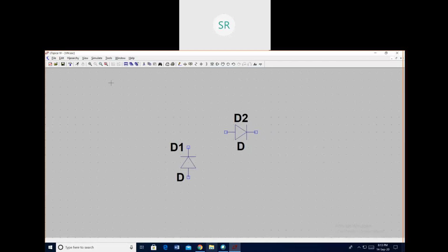So I want two capacitors. Capacitor 1. So I'll change the direction. So plus and minus. Sorry, horizontally I want to keep the capacitor. Here also I want to keep the capacitor vertically. Use Ctrl R. So place it in the appropriate place now. Now diodes and capacitors are placed.